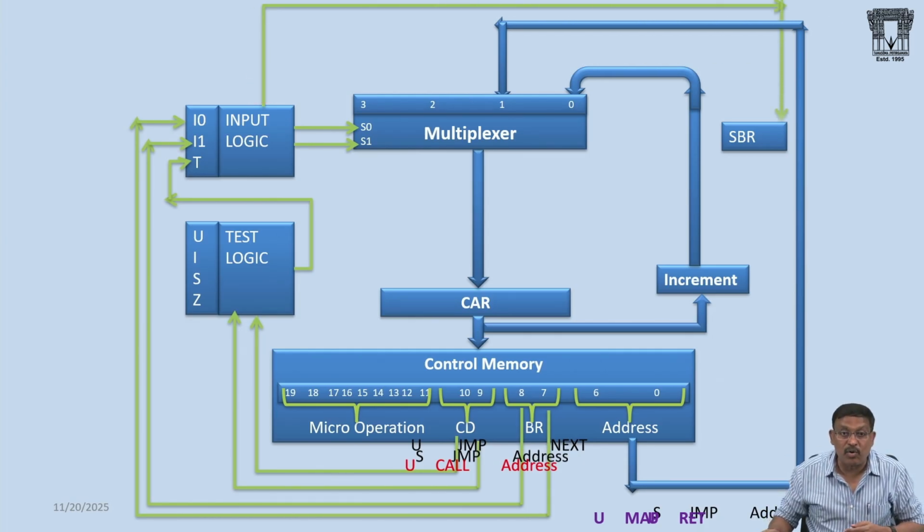So the load control variable is released by the input logic. If the load control variable is released, now the incremented value, that is the next address in a sequence, is loaded into the subroutine register. Right? See, this is then the return address. We are loading the return address into the subroutine register. You got my point?